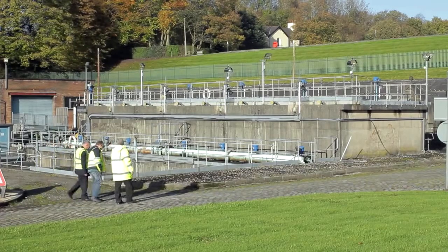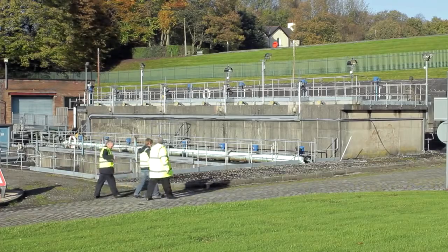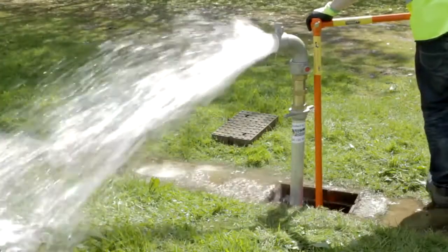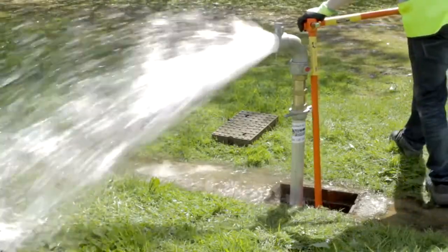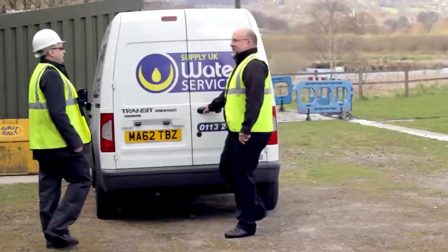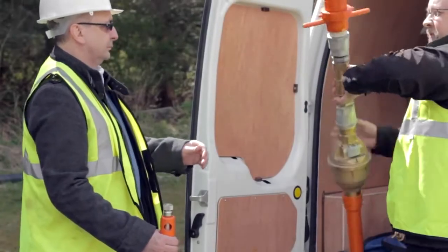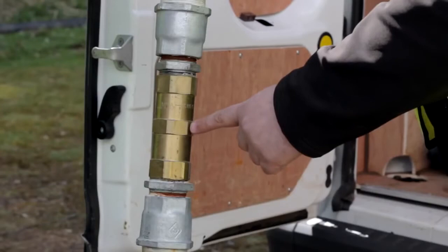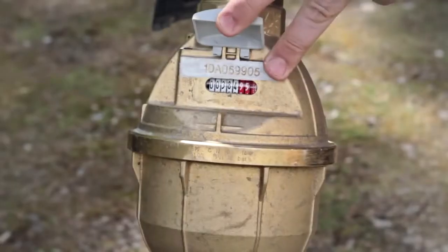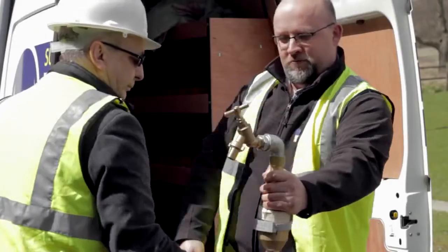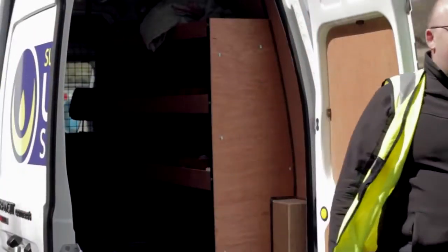Also, environmental considerations should be made. Where is any wastewater going? It could be a criminal offence should the water enter a watercourse. On collection of the standpipe, have you confirmed with the appropriate authorities your intentions to use it? Some water companies may give specific instructions. However, you may also need to inform the local highways authority if erected in a traffic sensitive area.